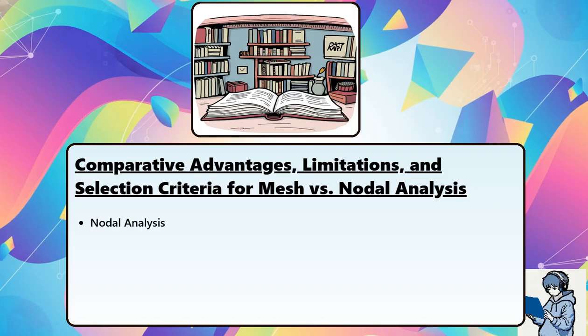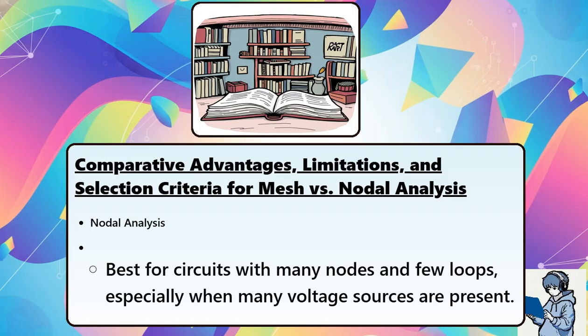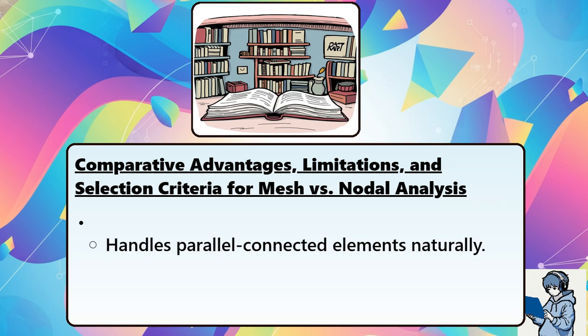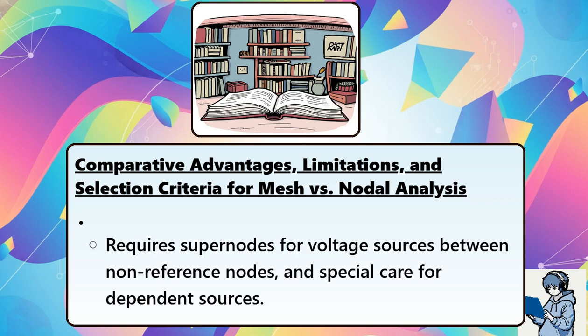Nodal analysis. Best for circuits with many nodes and few loops, especially when many voltage sources are present. Number of equations equals number of essential nodes minus 1 ground. Handles parallel connected elements naturally. Requires supernodes for voltage sources between non-reference nodes and special care for dependent sources.